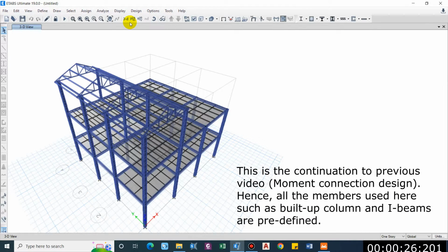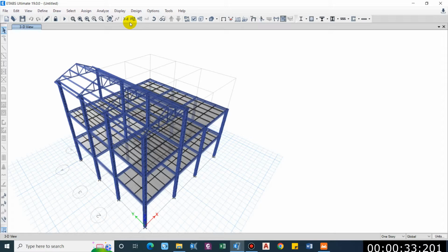So basically there will be a moment connection, shear connection, gusset connection, splice connection, and these all have their own definition. For moment connection, there will be the transfer of moment from one member to another through that connection. Shear connection has the transfer of shear from one member to another. Similarly, gusset connection primarily transfers the axial force but also minor shear and moment. And basically gusset connection, you can find that for the column and the base plate. And similarly we have a splice connection, used for connecting two members.